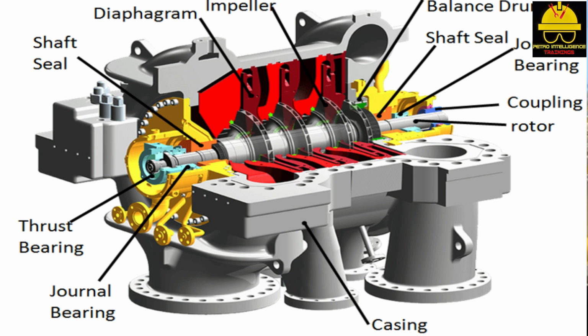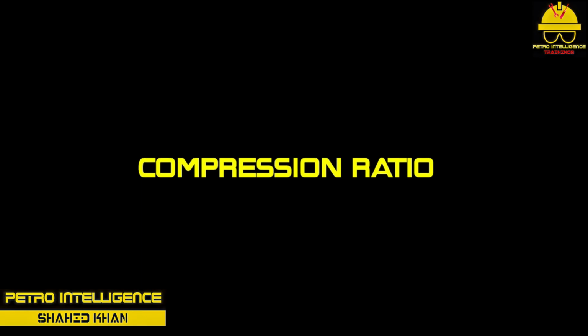Single-stage centrifugal compressors are designed for high gas flow rates and low discharge pressures. Multi-stage compressors are designed for high gas flow rates and high discharge pressures. Centrifugal compressors are also used for transferring wet product gases that typically damage positive displacement compressors.